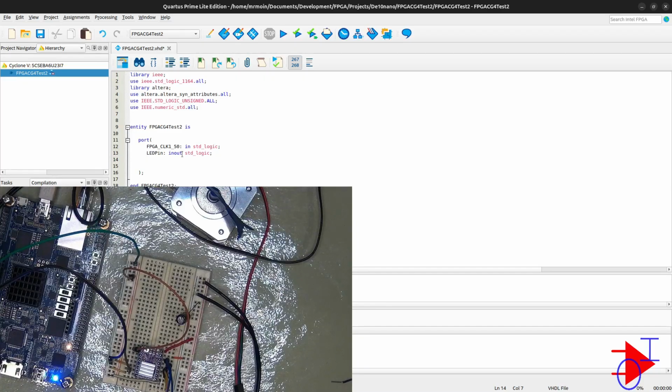That means that I can read the LED pin state, which is the out property, and in is the write property of the LED pin. It's a single bit STD logic. I'm just saying that this is the logic type, so it's a single bit, and we can read and write. We'll get to why later on in this code. Just hold on with me for a few minutes more.